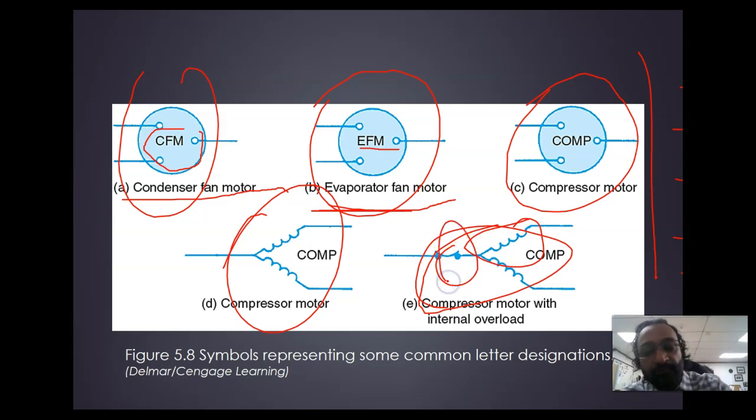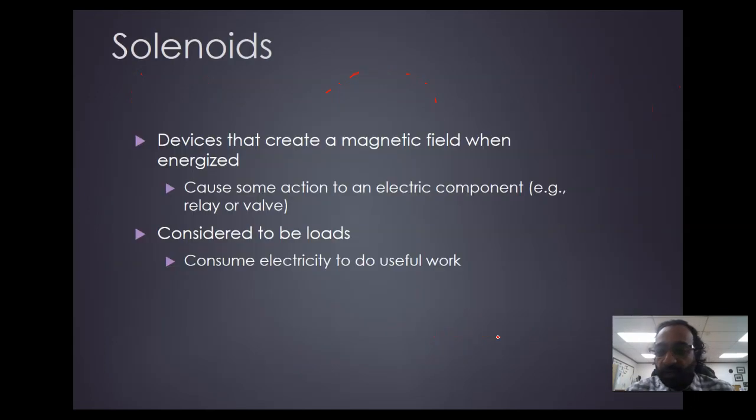What do you think this is here? This is probably a contactor. Actually, this is a compressor motor with an internal overload. This is an internal overload, and it's actually put in with the winding. So there's an internal overload inside this motor to prevent it from overheating.